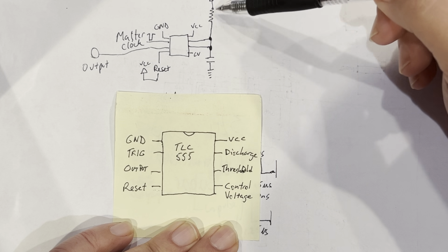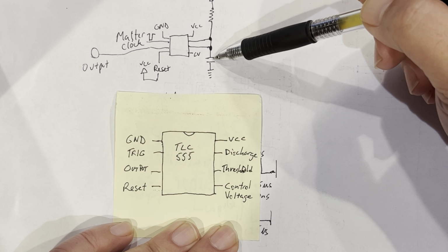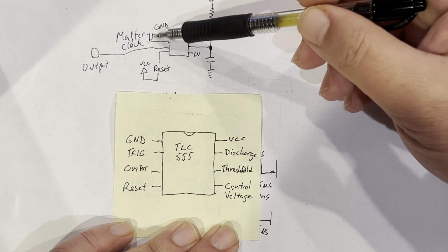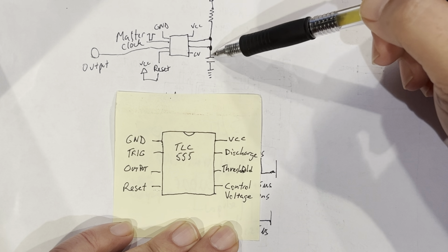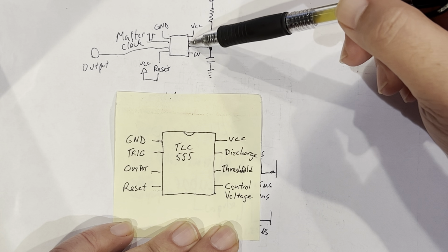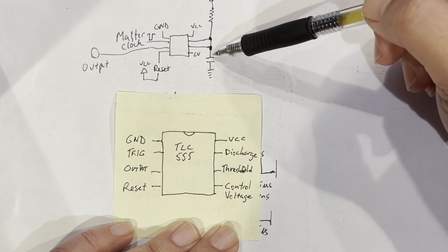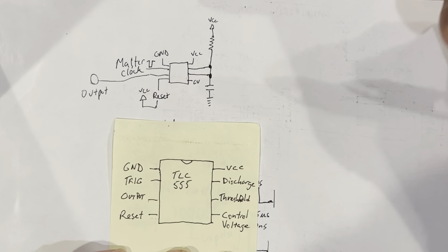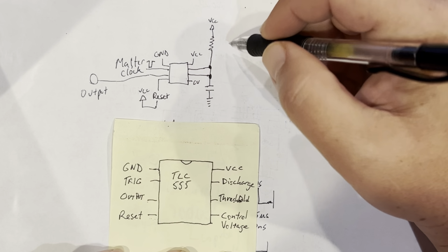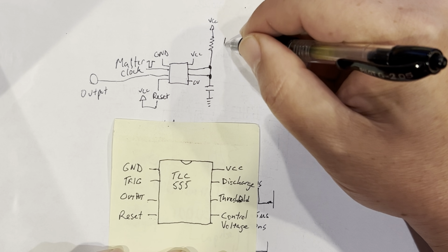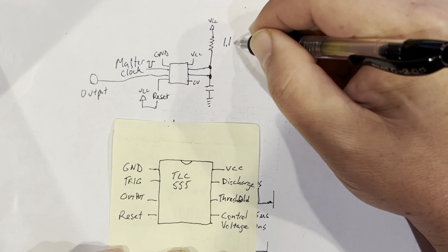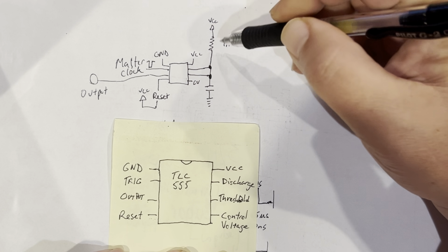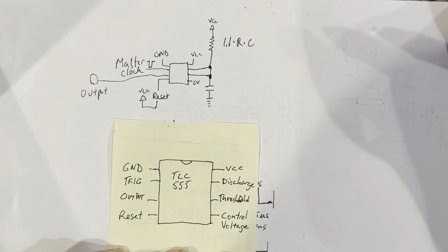This turns off pin 7, triggers the capacitor to charge through this resistor. And then the minute it's charged above a certain threshold value, 2/3 of the VCC, the capacitor discharges through pin 7 to ground. And the formula for calculating the amount of time for this total cycle is 1.1 times R times C, the value of resistance times the value of the capacitance.